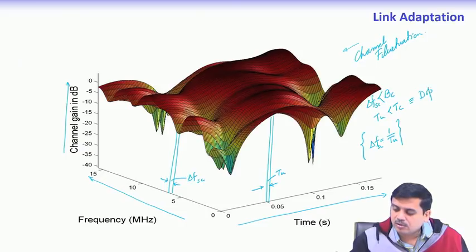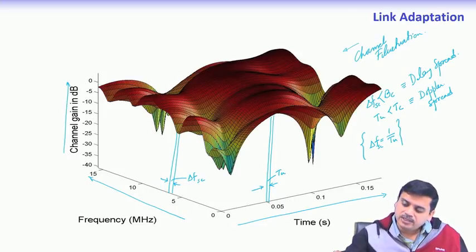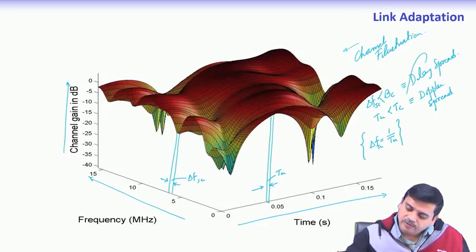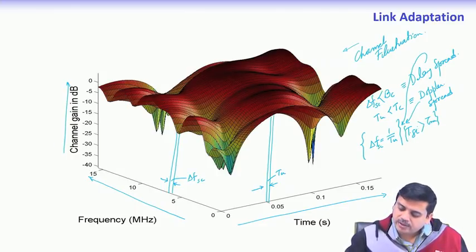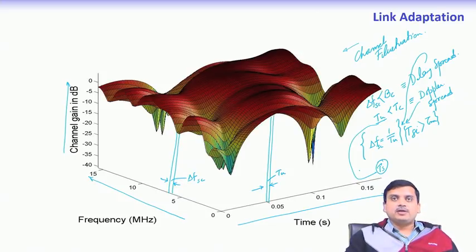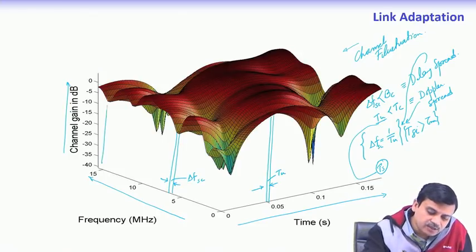This is due to Doppler. We can write Doppler spread, and this is due to delay spread, right. So, these two parameters influence the choice of subcarrier spacing and Tu, as well as Tgi should be greater than tau max. Okay. So, not only Tu, this we should replace by Ts to include the guard interval. Okay. So, that is the overall picture one should remember.